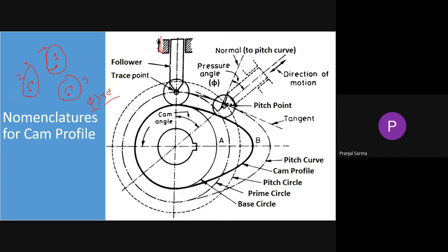Okay, and that's why generally we keep it lower than 30 degrees, for being safe. The pressure angle also depends upon the angle of ascent, the lift of the follower, the follower motion, and what kind of offset there is. Because it has so many roles to play, most importantly regarding the limitation of the side thrust in your work, and apart from that, jamming that particular bearing, etc.